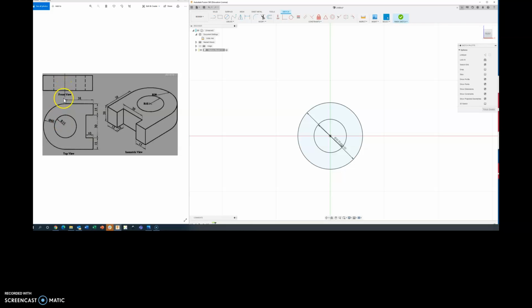So what it's showing you is the center of that circle lines up with this 38 millimeters here, okay? So what I can do is come over here to the center of my circle and come out to the edge, and I'm just going to draw a line tangent with the edge and descending 38 millimeters down at 90 degrees. So now I can just type 38, press enter, and then I've got these little feet